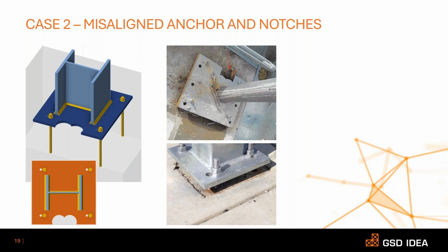So in real construction, anchor bolts often shift during concrete casting. In some cases, the people who design this used to give big slotted holes in order to accommodate these shifts. However, it won't be done in all cases.